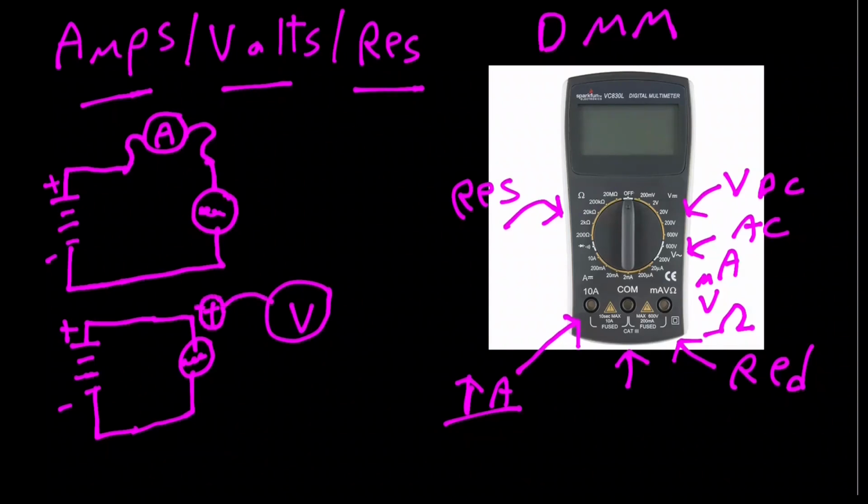And you're going to put the probe here, and the negative end of the voltmeter, the black wire, you're going to measure here. Okay, so you see you're measuring the voltage with reference to the positive and the negative across the components. It is not in series. It is hooked up in parallel with the component you're going to measure if you're going to measure voltage. And if you're going to measure current, you put the meter in series with the circuit.